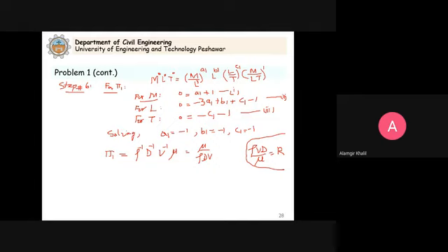This is the power of dimensional analysis, even though it does not provide a complete solution. So this means Reynolds number has no units. It means this is correct, no dimensions, because we already know Reynolds number has no dimension. So this is a check on the calculations.